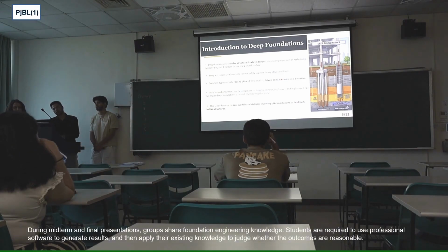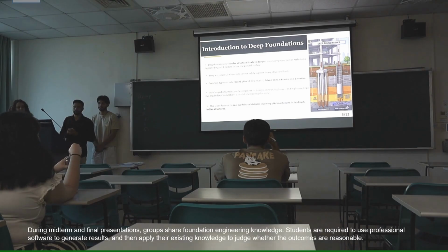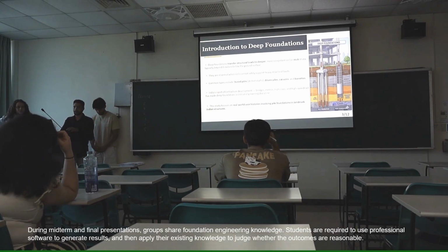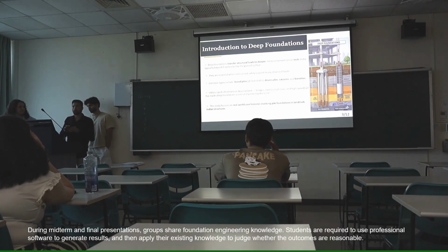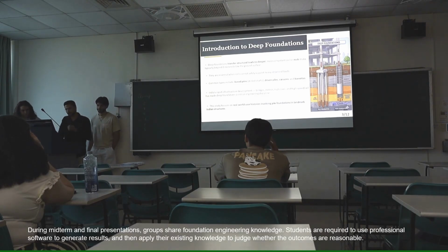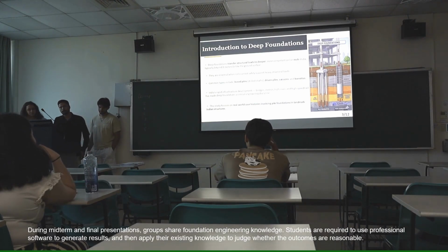First, we know what the deep foundation is. It is used to transfer the heavy structural load of the building deep into the ground or to hard strata like rock layers, and it is used where the top surface soil is weak and unable to carry the load. Sometimes it is used where the water level is high or nearby river sites where scour can happen, and sometimes it is used to reduce the settlement also. Some common types are bored piles, driven piles, caissons and piers. In India, deep foundations are used in bridges, metros, skyscrapers, high-rise buildings and high-speed rail, making them the foundation of critical engineering disciplines.